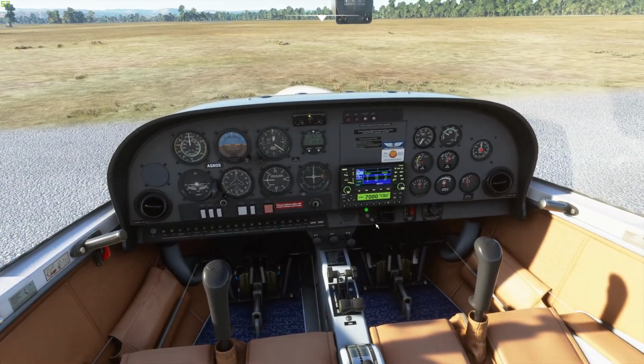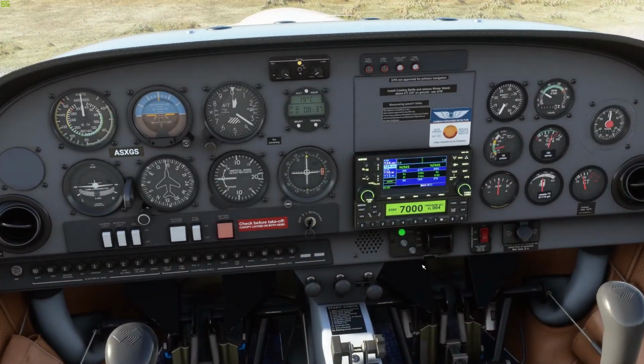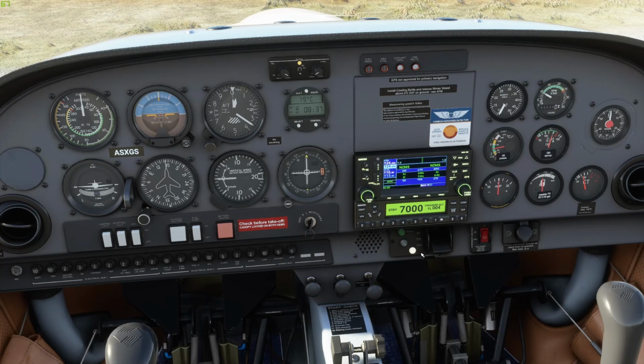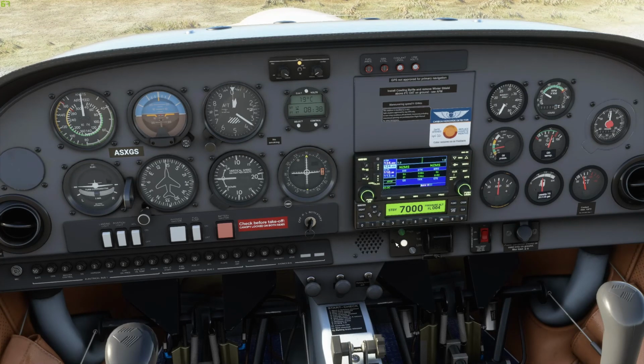That's about it. So there's 3 stages of flaps. We can have a look at that now. So there's a takeoff setting, that's indicated by a white LED, and a full setting, still also a white LED. So if we see white, we know that we've got flaps out. If we see green, we know the flaps are up. And it looks like it only indicates when the flaps are in that position as well. So that's kind of cool. Okay, I'll just set 1200.